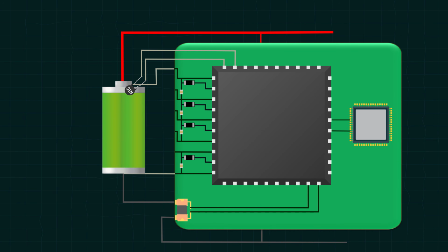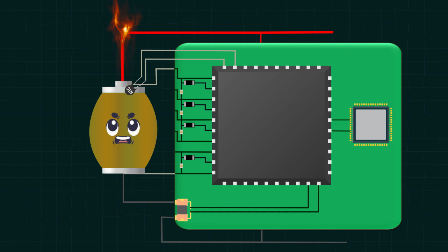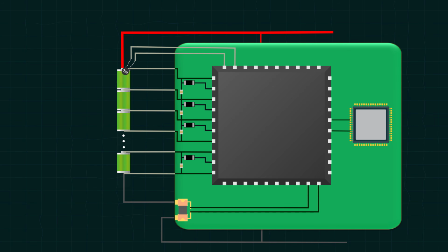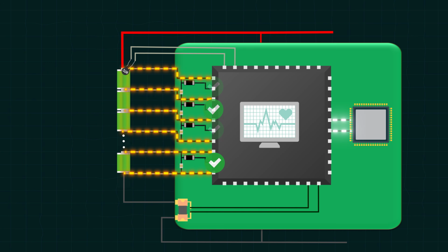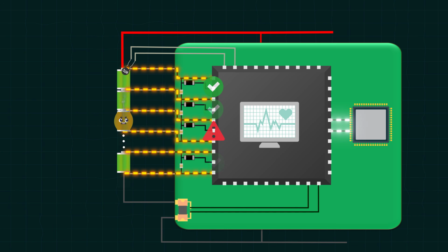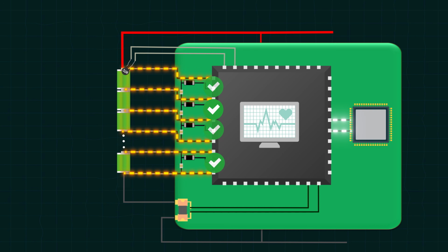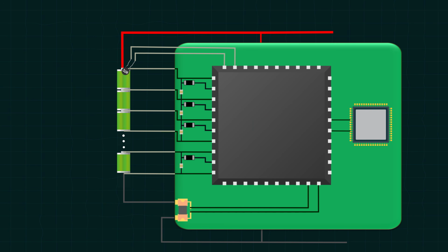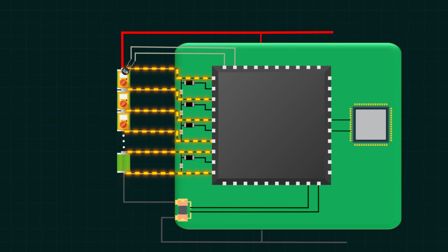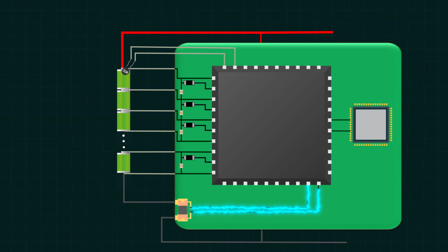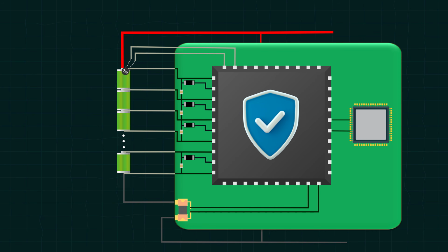Low voltage systems like 48-volt batteries in scooters and e-bikes can still overcharge, overheat, or get out of balance. An AFE is the watchdog that monitors all these cells and makes sure nothing goes boom. In fact, for low voltage BMS, AFEs are often optimized to be simple and cost effective, but highly accurate for measuring voltages and shunt currents. Using an AFE in these systems simplifies the design and boosts safety.